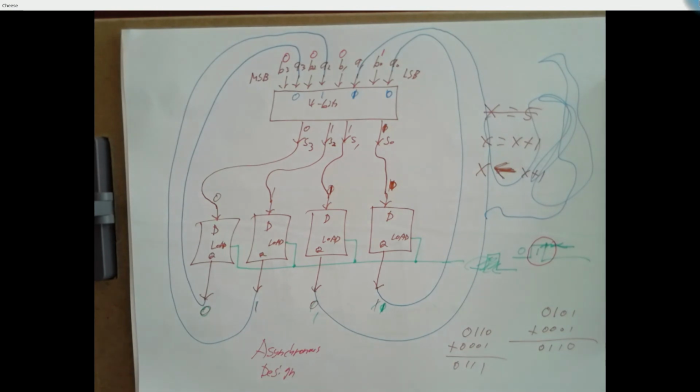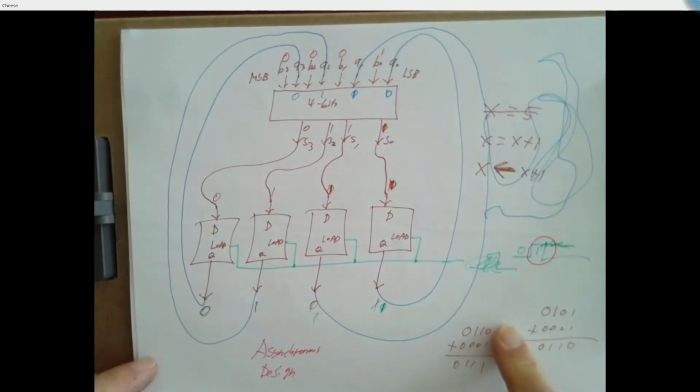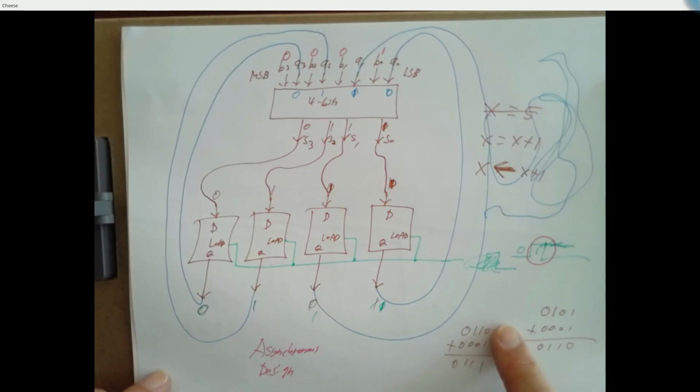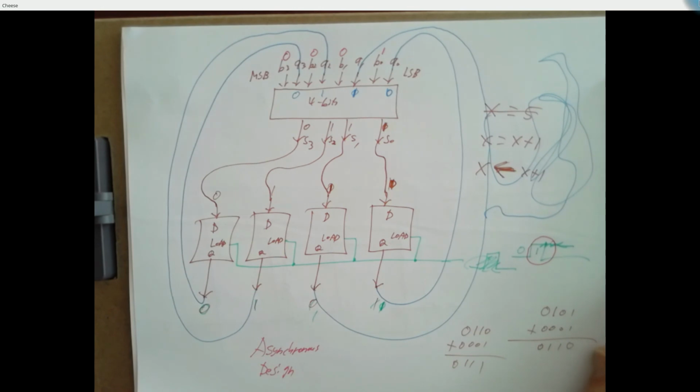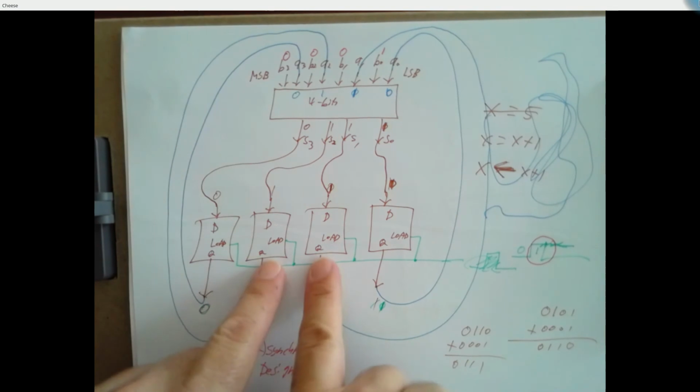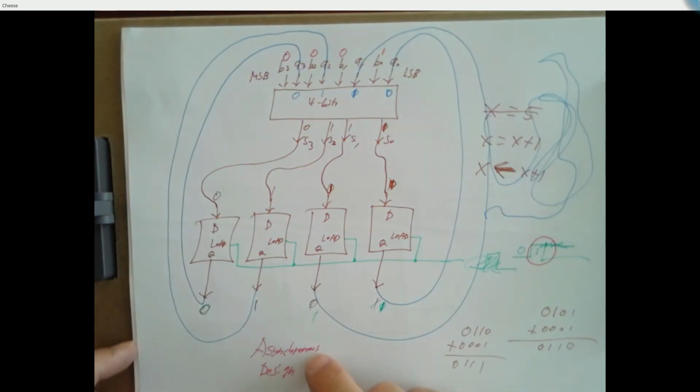Yeah. To make this design work, you would need like a perfect environment. Yeah. And you need to know exactly how long you should keep this thing high and then drop it. Like some complex mathematics. Well, yeah, and classic story, you get your circuit and it's working great in the middle of the night. When you finished it, and you come into school the next day and it's 80 degrees in the room, and it doesn't work anymore because the switching times of these things are temperature dependent. So yeah, it's a real challenge.